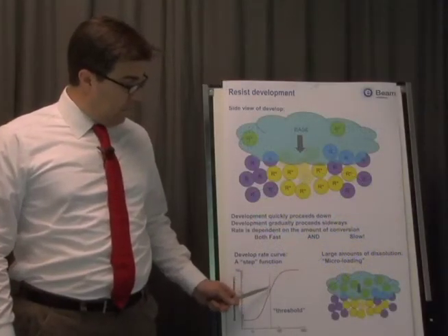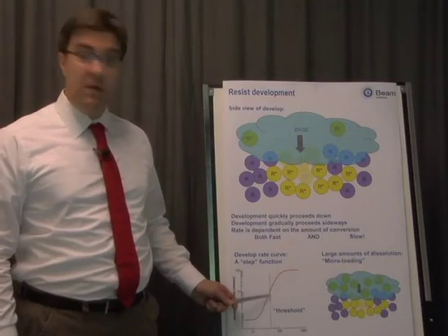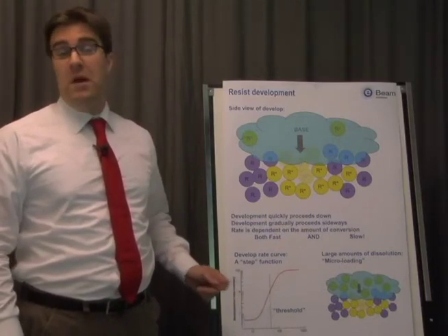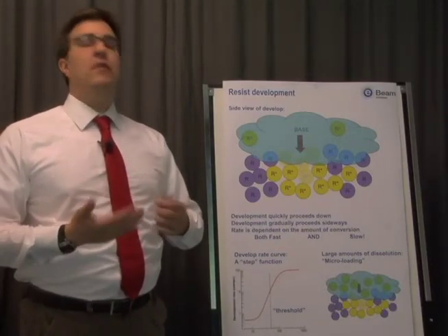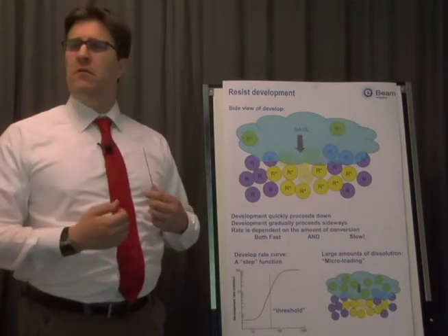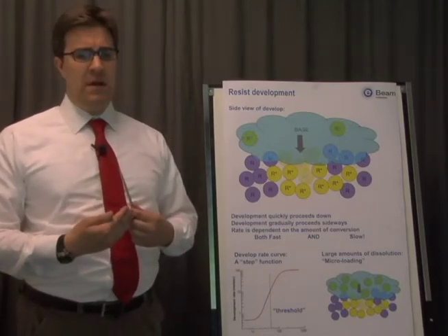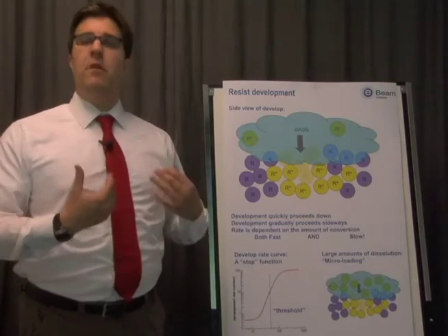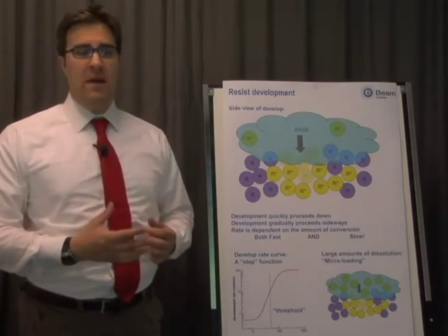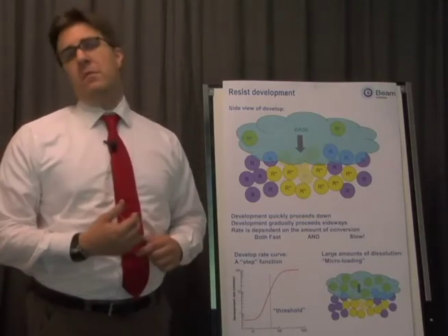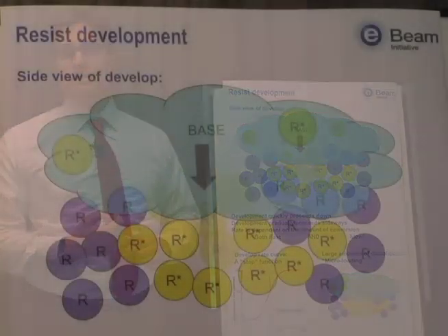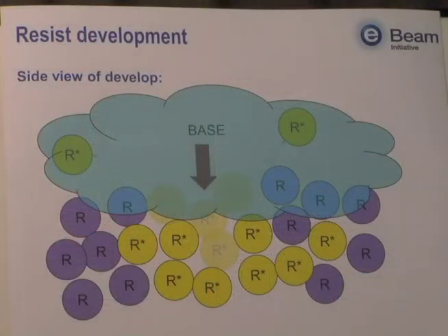So this threshold of solubility gives rise to a threshold of acid concentration, which then gives rise to a threshold of eBeam exposure, which gives rise to the concept of a constant threshold model that we use in mask modeling today. Unfortunately, this idea of a step function switch to solubility is not quite borne out in reality. In fact, the rate curve is somewhat more broad, but that gives rise to some other interesting physics.